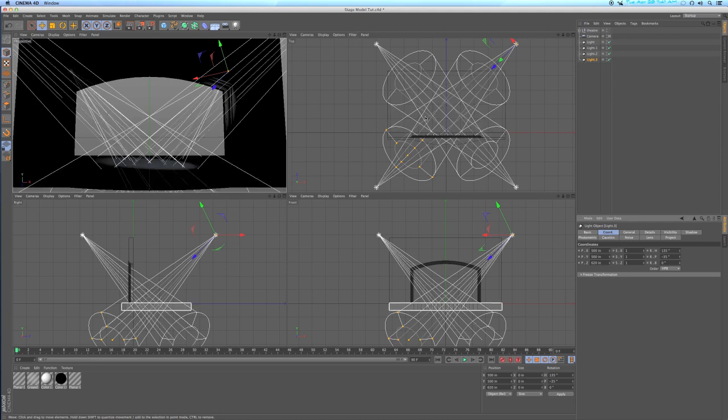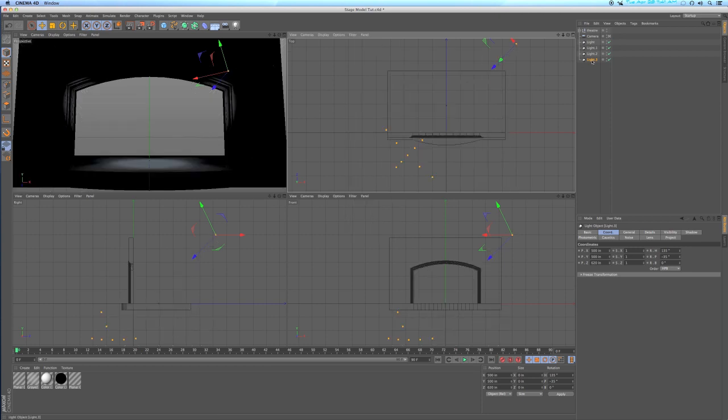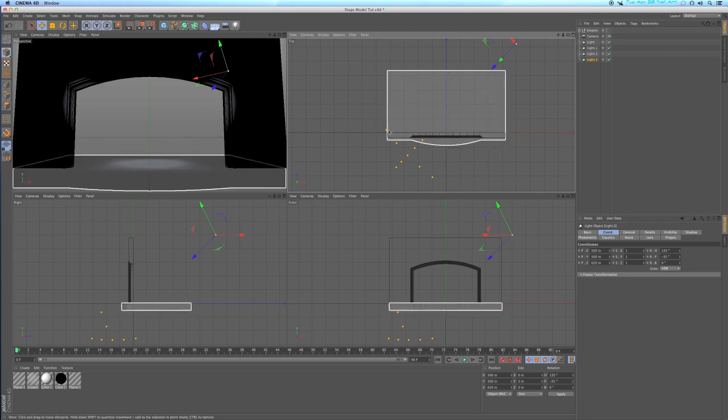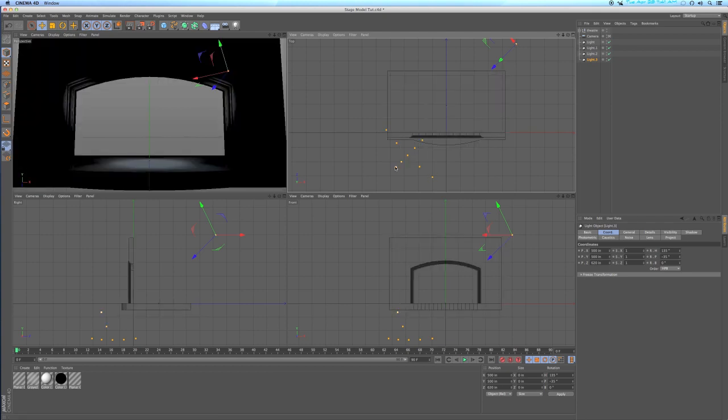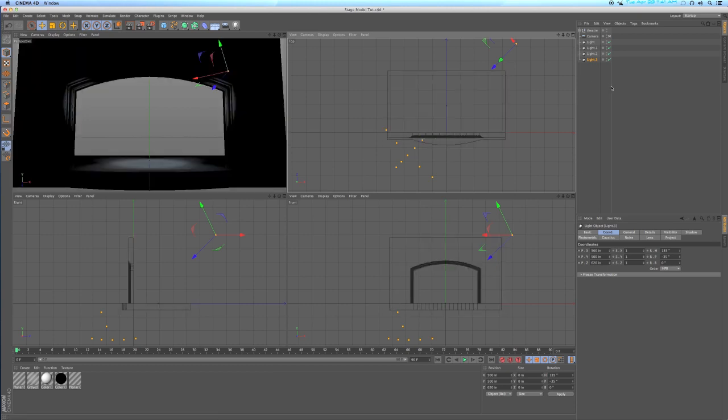Having all these lights, it gets very confusing in all the different windows. It's just too much information. That's why I always, in the filter, I deselect the lights so that I don't see them. When you have a light selected, you can still see the point of its origin, and you can see the point where it ends in each of the different windows. Okay?